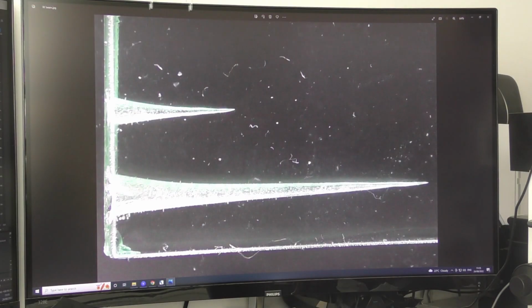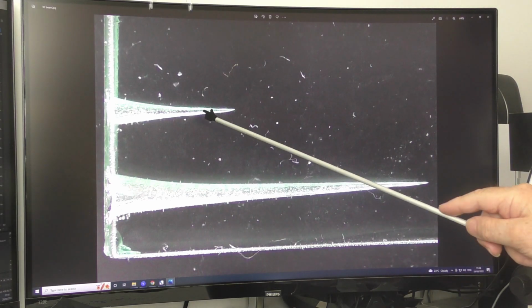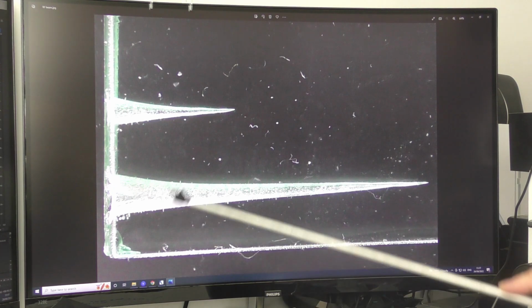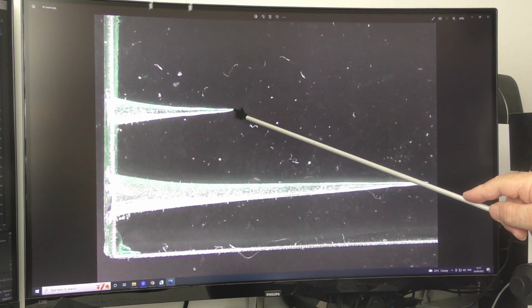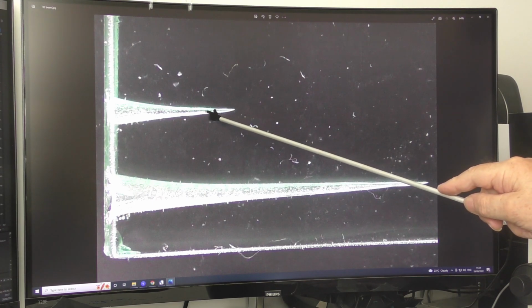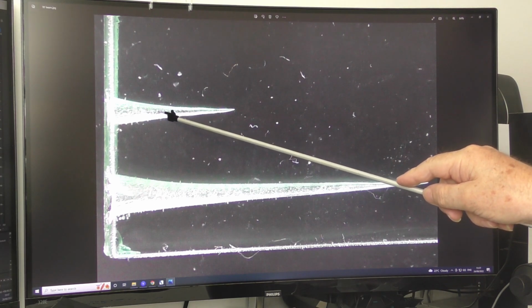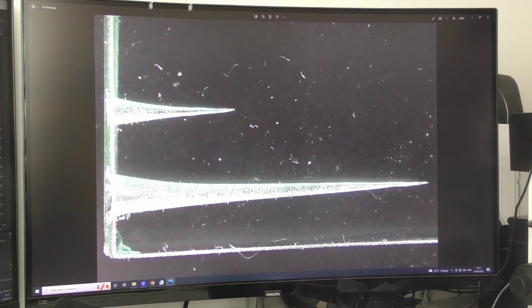I will just remind you of the peculiarity of the RF machine. When the aliasing reaches a point where, as you saw, we get no output power, the problem with an RF tube is the power is always 100%. The thing that's changing is in fact the exposure time of that power, and as that exposure time increases, the beam size, the dot, is increasing in diameter. So we're not getting a change of power directly, we're getting a change of exposure time, which changes the dot size.